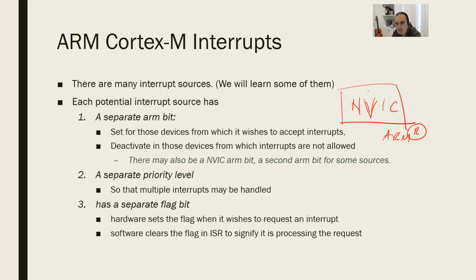It's a separate thing. We are going to talk about this. There's a second bit there you should also enable. So what I'm trying to say is simply, for some interrupt sources, to arm the interrupt, you change one bit. For some interrupt sources, you change 2 bits in 2 separate control registers. Which control registers? Where are they? For which source? All written in the datasheet.